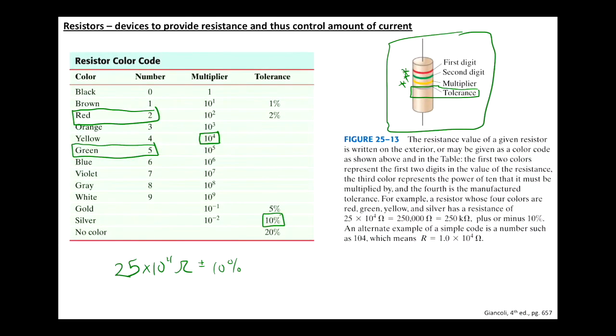If you're sitting back thinking, how do I know which direction to read the bands? Well, that last one is always going to be gold or silver. Start from the other side. Okay? Any questions or thoughts there? I think perhaps, maybe you can handle that.